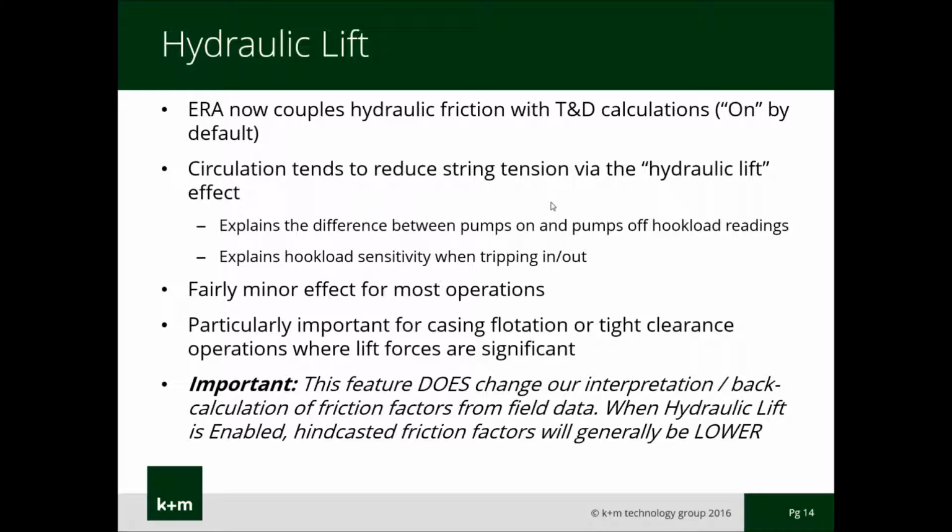For most operations, the hydraulic lift effect is fairly minor and there's not much consequence by ignoring it. However, for floated casing or tight clearance casing run operations, the lift force can be quite significant and it is important to take it into account.